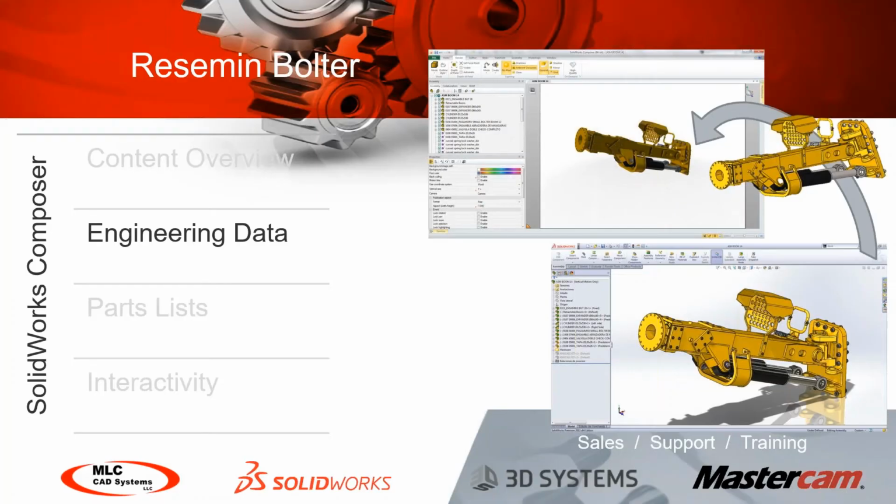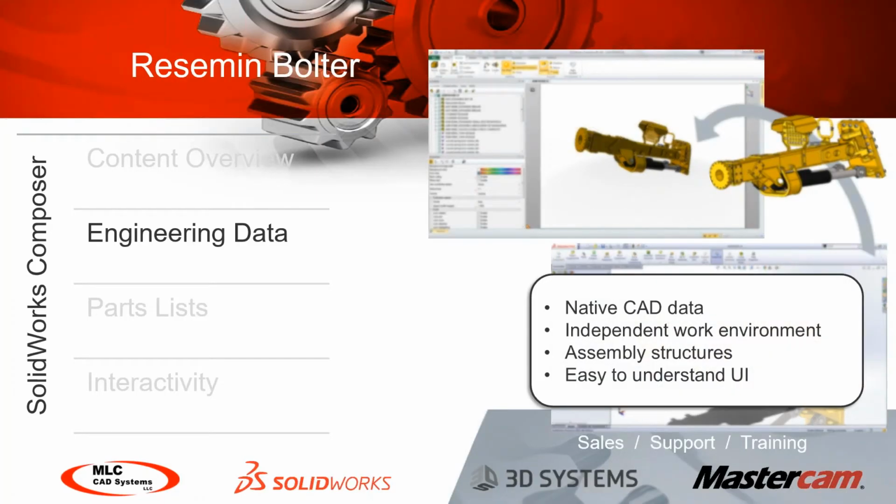So inside of SOLIDWORKS Composer, our engineering data is actually our native CAD data. We're working directly with our SOLIDWORKS files, but we're working inside of an independent work environment. Now, we still preserve all of our assembly structures, all of our custom properties, all of the information that existed in our SOLIDWORKS model. We've got it in a dedicated user interface that's very easy to use and very easy to understand.